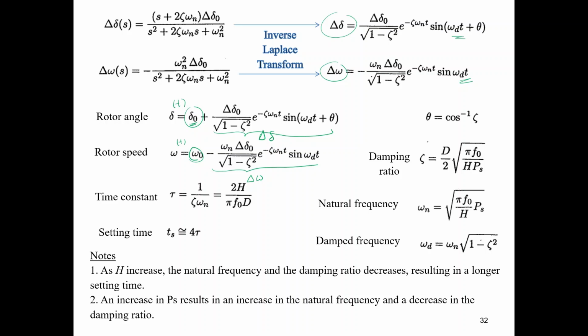Okay, now we see the notes. As the H increases, the natural frequency and the damping ratio will decrease. This is of course because when you increase H, the damping ratio and the natural frequency will decrease. So that will result in a longer settling time, okay?